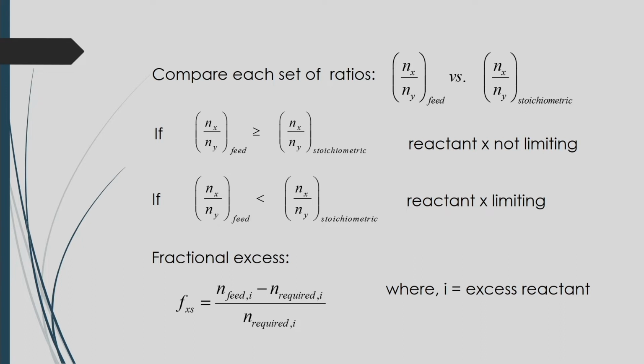And also, sometimes, for the amount of reactant supplied in the feed, you have to calculate what should be the actual amount of reactant required for your complete reaction theoretically, and after that you have to judge what excess amount of that reactant is present in your feed mixture, or if there is a shortage then you have to supply an excess amount of that reactant in the feed mixture, so that your reaction will be completed.